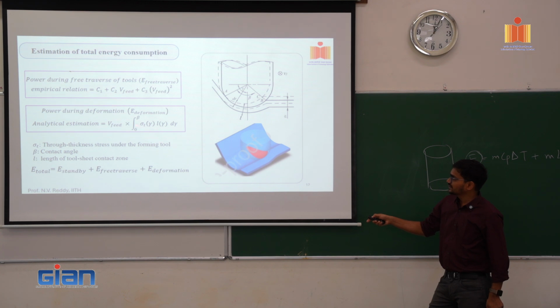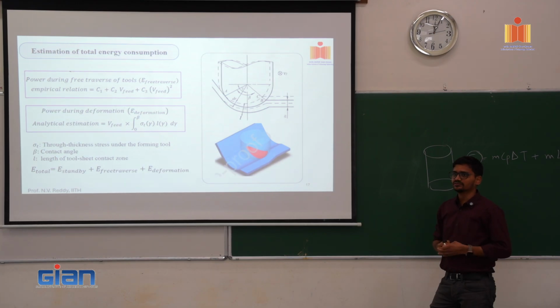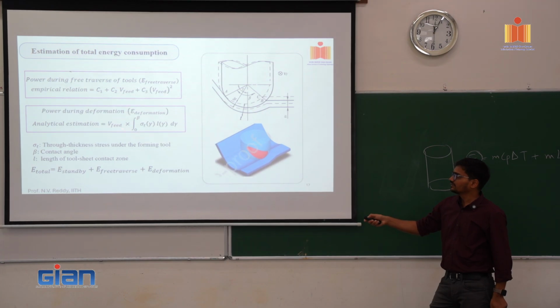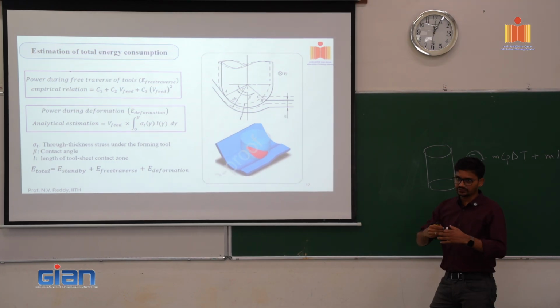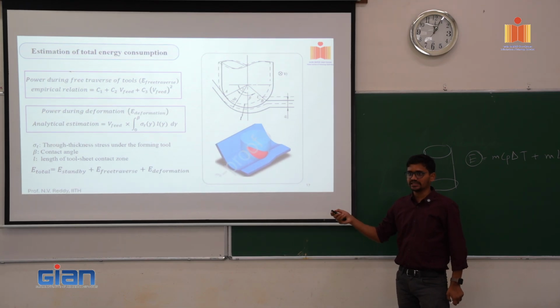And for the deformation energy, again we can do some fundamental stress analysis calculation that will give you the energy required for the deformation of the workpiece. For example, if you know the stress levels at each point, and if you know the geometry, then you can calculate the work done per unit volume, and then you can multiply it with the feed rate, and that will give you the energy per unit time.